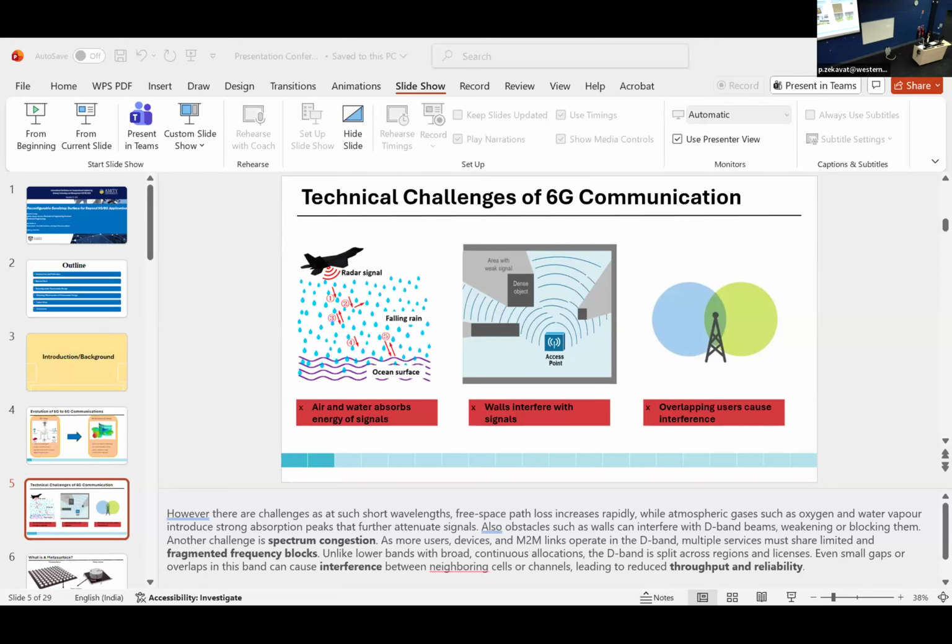So overall, this presentation shows how a reconfigurable bandstop metasurface can be electrically tuned with pin diodes to dynamically shift the stop band in the D band spectrum, showing suppression of frequencies that could be unwanted in 6G communications. Thank you.